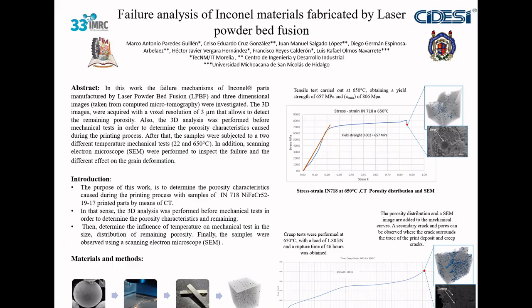However, porosity is one of the main challenges in the LPBF process and has a considerable impact upon the fatigue properties of a bulk. Porosity can be easily introduced by almost all AM process parameters. In order to prevent a failure, it is important to be able to determine the position, direction, shape, and size of the pores to know the final density of the piece that was printed.